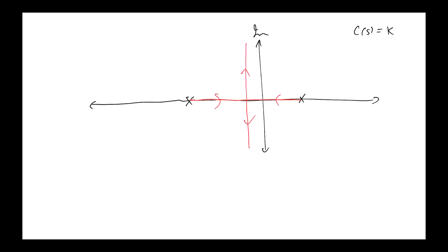And we saw that by putting a 0 and a pole such that the location of the 0 is closer to the imaginary axis than the pole, then we haven't changed the relative degree. So we're still going to get asymptotes that go towards the zeros at infinity as we increase the gain of the controller. So the blue controller here is something that looks like K (s plus z) on (s plus p), right?